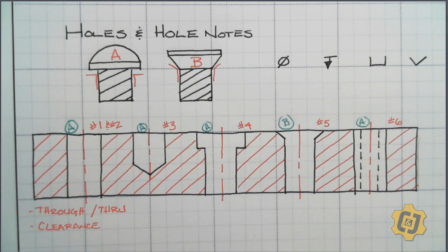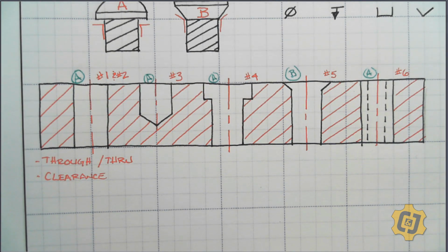Now I'm going to go ahead and scoot my page up, because what I now want to do is write the hole note for that kind of hole. So if I was designing this, yes, I would have to tell the manufacturers where it is, but more importantly, I want to focus on just the hole by itself. If I'm going to focus on the hole, there's really two things I need to tell them. I need to tell them how big it is and how deep it is.